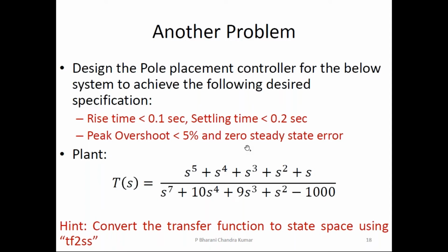So there you have to choose. Based upon your application at hand, as a control engineer, you have to specify your own desired specification. If it is a fighter aircraft, where we need very fast response, the settling time should be a few seconds. If it is a nuclear reactor, which is very slow, you need it in hours. So every application has its own desired specification. If you go for aircraft, we need maneuverability. That is a major problem in aircraft.